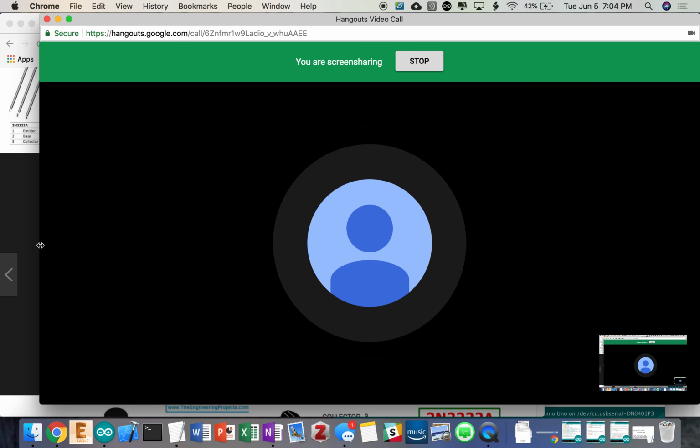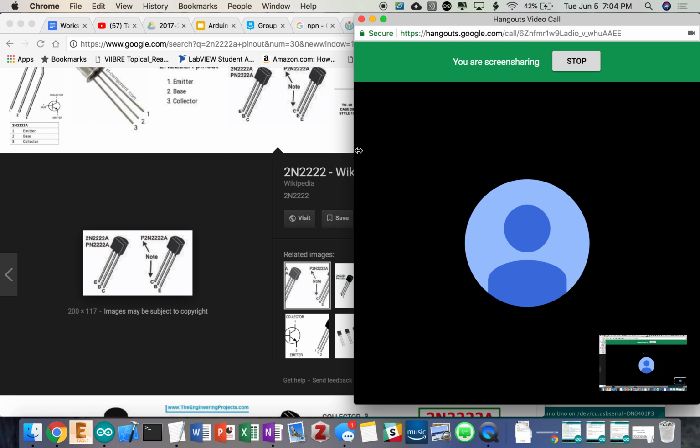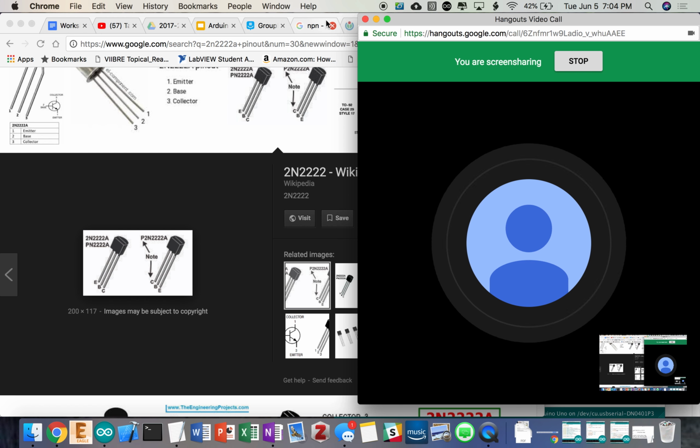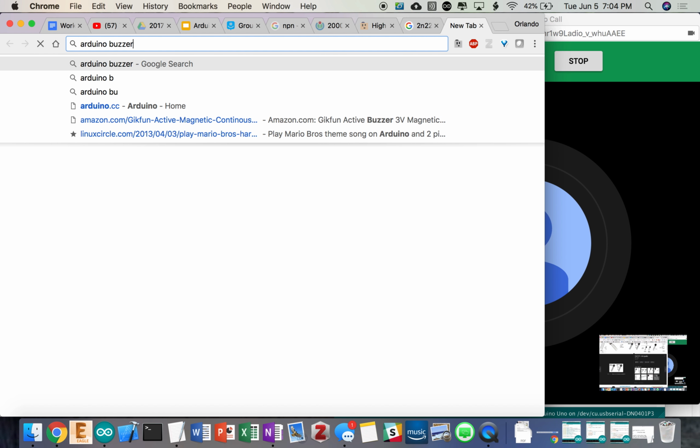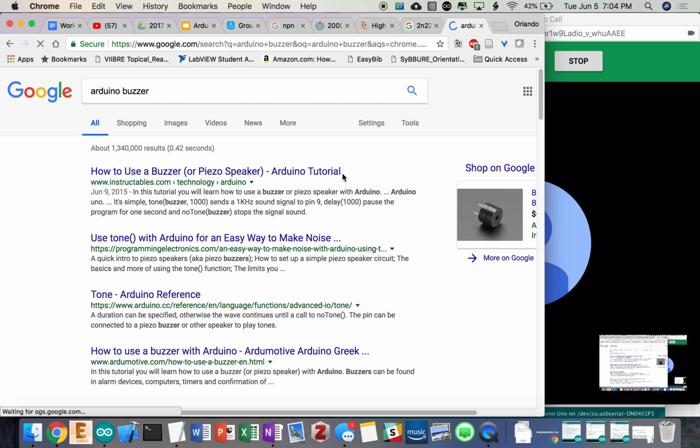I don't think I have any transistors unless... That's fine. You have the Uno though, right? Yeah. You can hook it up directly to a digital pin. You're fine. That's what I was thinking. By the way, is an op-amp technically a transistor? An op-amp is made up of transistors. Okay. But for this, if I put a buzzer, I put a resistor like a 57 ohm or so in series with my buzzer, but you're probably fine. I've hooked it up directly to the Arduino pin plenty of times, so you're fine.